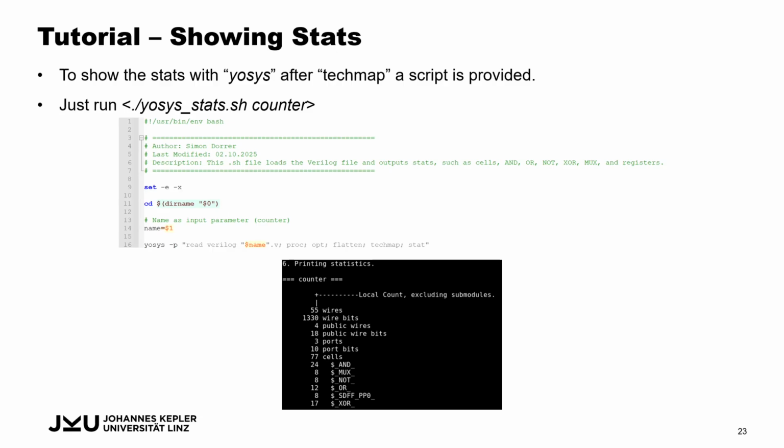And here we now have the component count from the tech map, which is more precise than with only process and stats, on the real solution in the end. And in this case, there is printed the hardware for an 8-bit counter, and we see the 8-bit registers in there with some additional logic, and of course some wires to interconnect everything.